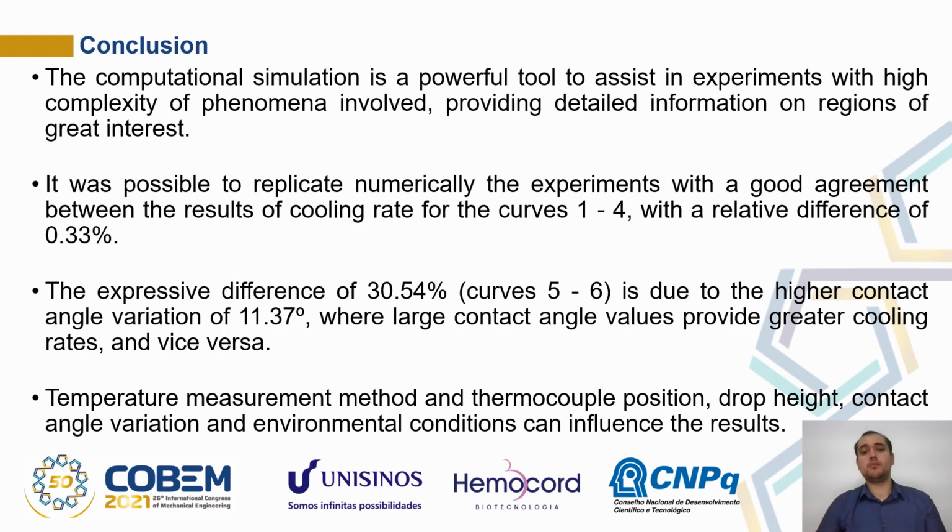So, the computational simulation is a powerful tool to assist in experiments with high complexity of phenomena involved, providing detailed information on regions of great interest. It was possible to replicate numerically the experiments with a good agreement between the results of cooling rate for curves 1 to 4. The expressive difference for curves 5 and 6 is due to the higher contact angle variation, where large contact angle values provided greater cooling rates and vice versa.